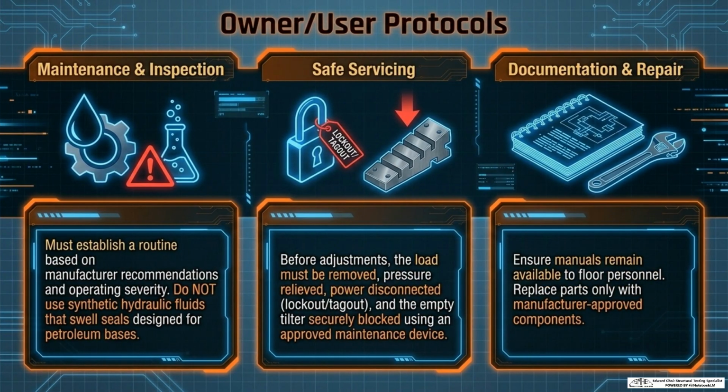For owners and users, the standard translates to 3 practical obligation areas. Maintenance and inspection must be routine, frequency based on manufacturer recommendations, and operational severity. One specific caution: do not use synthetic hydraulic fluids that swell seals designed for petroleum bases. It is a common and costly mistake.